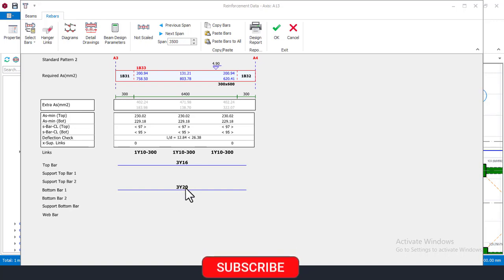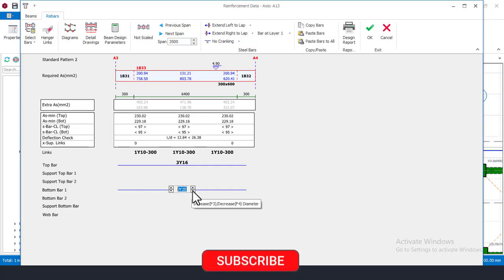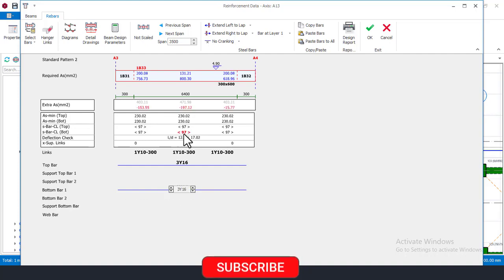Right now I'll try to check if I can use four numbers of Y16 for this, and I'll reduce the diameter of the bar here, and there will be a failure. I see that it is failing right now. I'll have to come here and increase to 4Y16 here. Once I increase it, basically it is okay, but put your eyes here on this place that says extra area of steel.